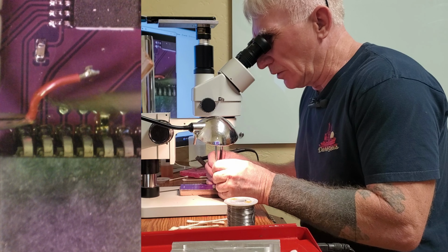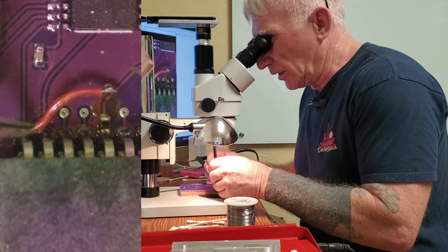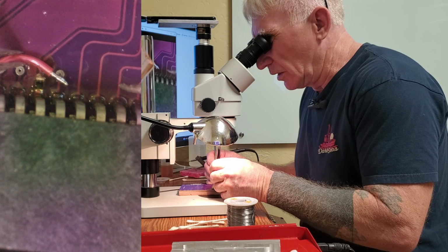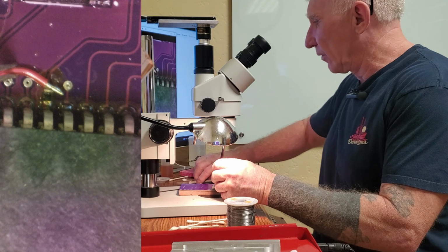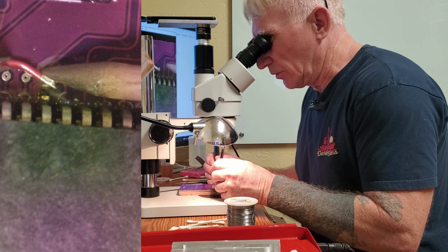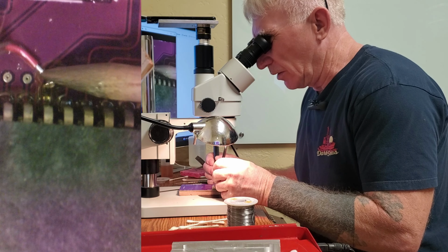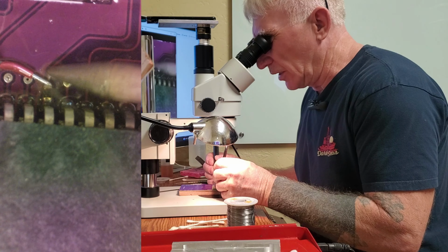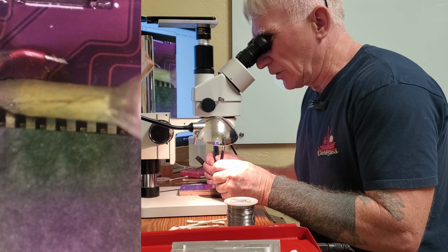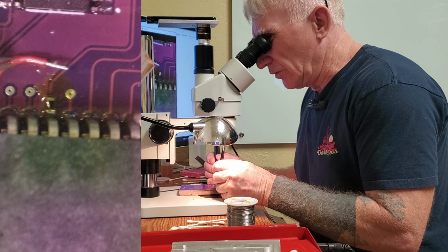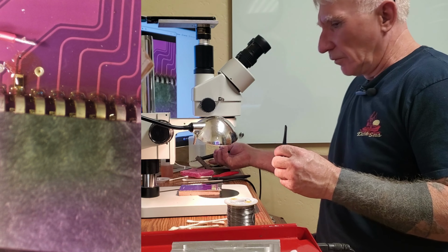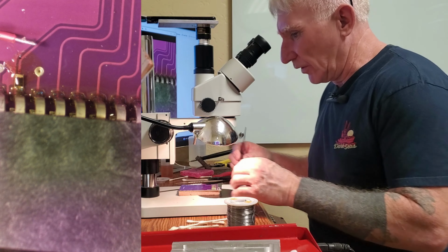Without slipping and, yeah, I think I broke the resistor. See if it'll stick back on there. Sometimes it'll pull the coating off the resistor and it won't stick anymore. Yeah, that's what we did. We broke the end off the resistor. All right, so we're going to have to put another resistor on there. So let's solder that to VDD like that. And we should have probably done that first.